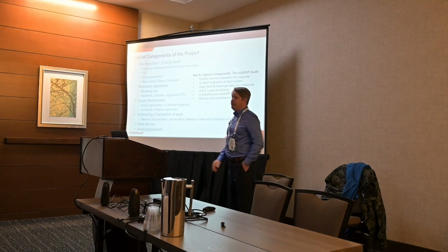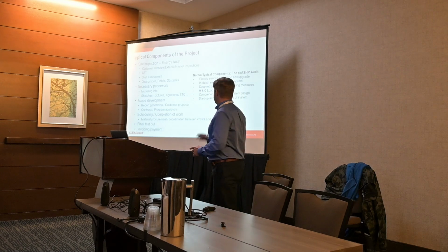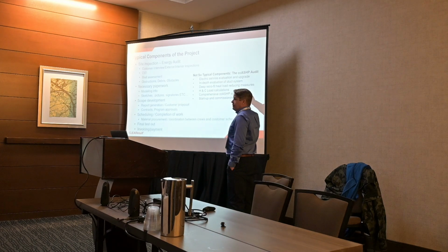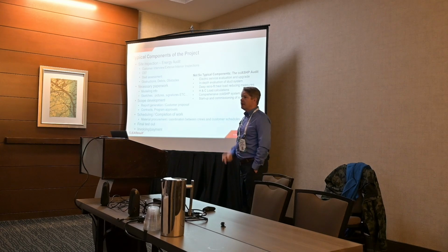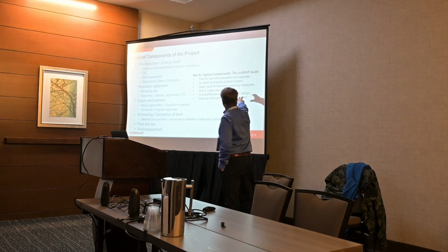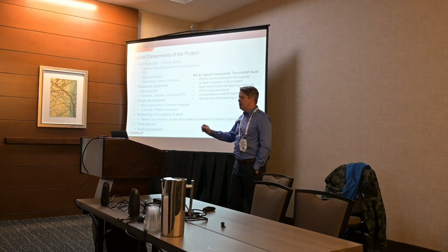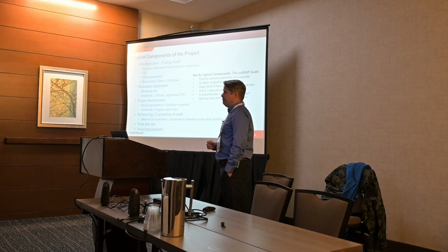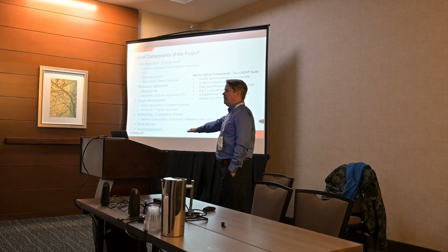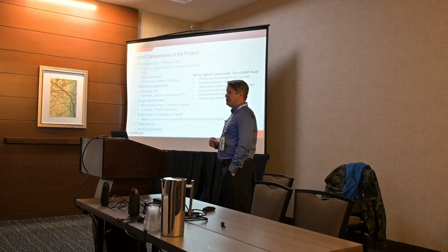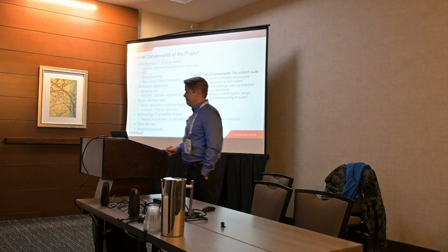Somebody needs to design it, okay? It's great to have a heating and cooling load calculation, but there are other parts to it. We need to take that and take the procedures in Manual S, ACCA's Manual S, apply those to the load, and pick the right unit. And when we do that, we also have to design the duct system, and we have to think about zoning and matching up the units exactly, or as exactly as we can, with the loads that are in each room, okay? This idea that we can do one outdoor unit, one indoor unit, that's not the way to go, okay? That's expensive, first of all, and you get oversized. We can't do it that way, all right?